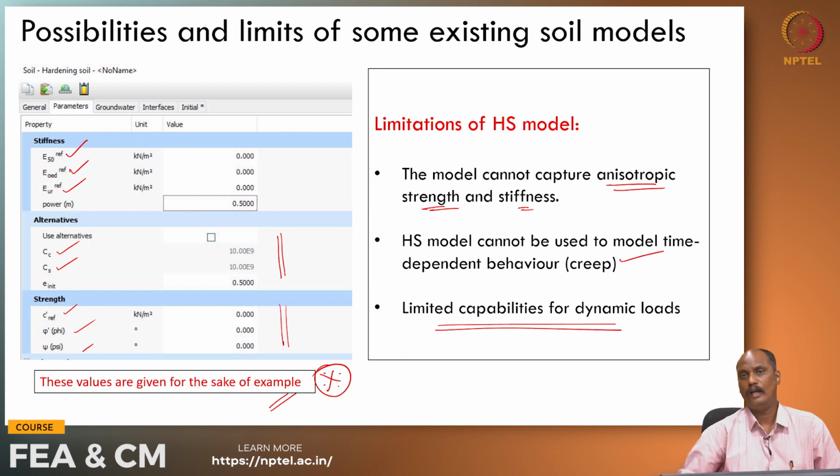Again I would like to remind you that all these input parameters should be taken from laboratory tests, and if we want, field tests also. The more complex the soil model, the more parameters are required from either the laboratory or the field to capture the real scenario.